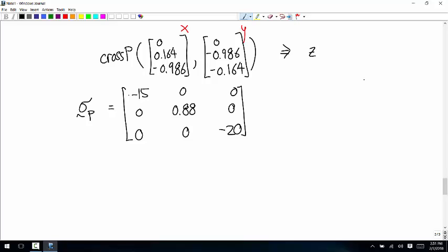Why not just use the third axis that they give you? Those are not necessarily right-handed. It gives you three eigenvectors that correspond to the three eigenvalues, but it doesn't make sure that they're a right-handed coordinate system. It could be positive or negative. If you assume that these are x and y, and then find the perpendicular one, and compare it to that third eigenvector, you'll see that they're parallel.